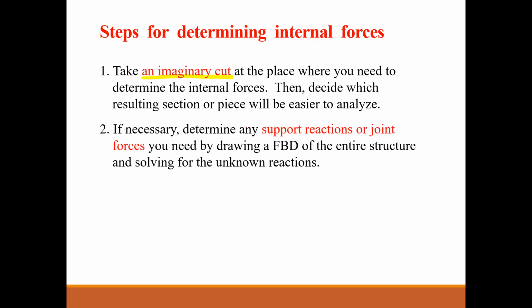The next step is to find the support reactions. Maybe it's better to find the support reactions first and then use the cut, but sometimes, like with trusses, we just need to analyze half of the structure so we don't have to find all the support reactions. So the next step is always finding the support reactions.